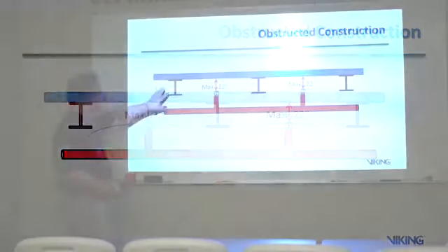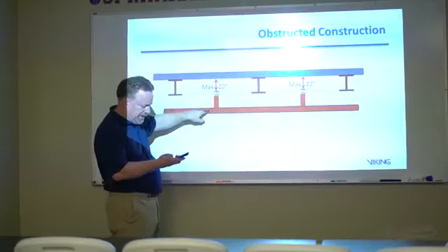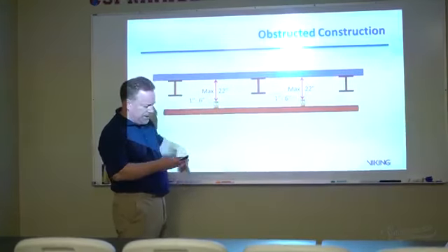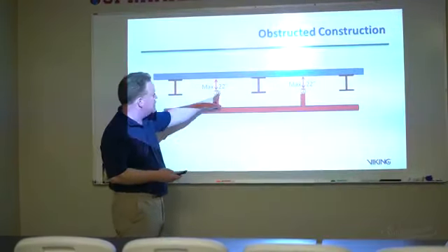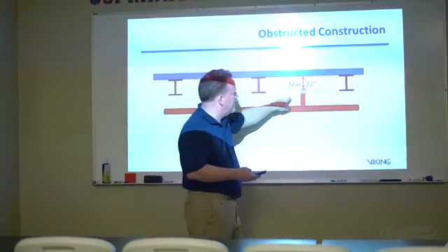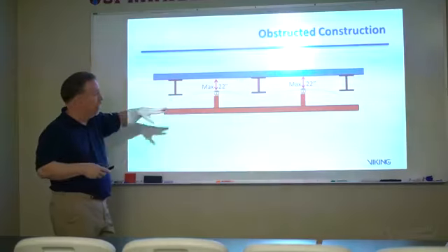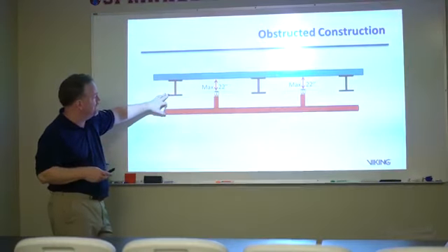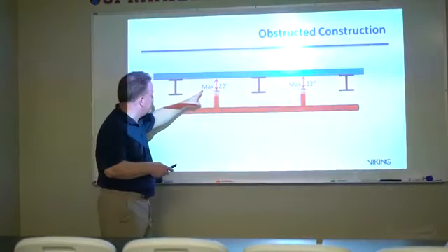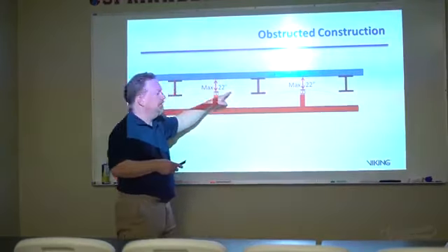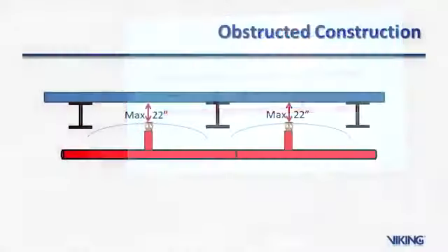Now, if you're going to put sprinklers in this, you're going to put sprinklers down below. Now you could put sprinklers up on the same level. That's one of the things that they could have done with that type of construction. One of the things you can do is put your deflector right up at the same level as the bottom of the obstruction.